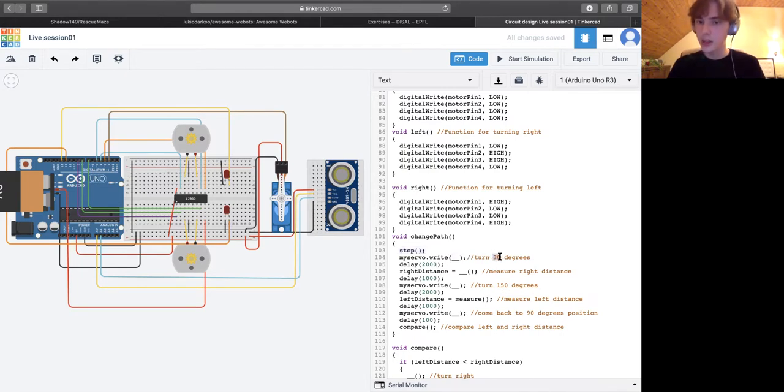And here you can note that we're using 30 degrees. You may question, why are we using 30 degrees and not 0 degrees, which would correspond to the left? Honestly, it's due to safety, since from the practical perspective, it doesn't make a huge difference if we measure the distance at 30 degrees or 0 degrees. However, it provides us with a safety factor, since in many cases, servos can actually turn more than expected.